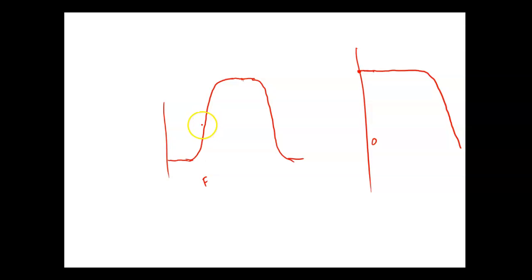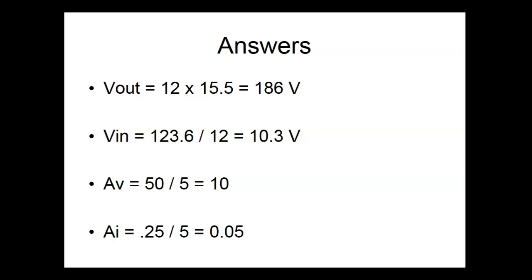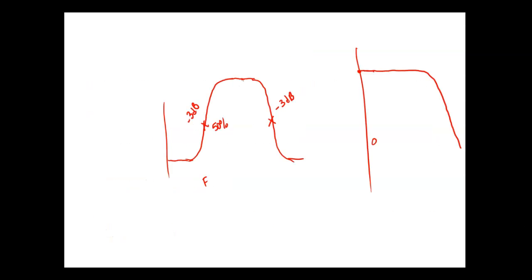So this would be 50% power, or minus 3 dB. And this right here would also be at 50%, which people say is minus 3 dB. So you'll see 3 dB all the time when you deal with it. That's the 50% power point.